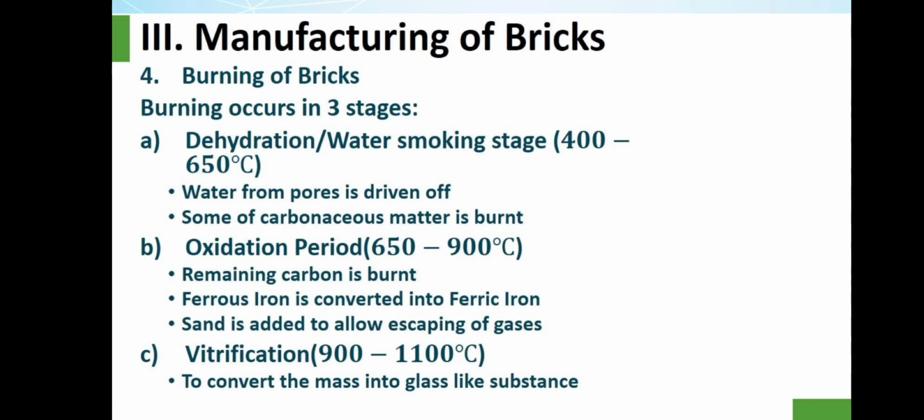Fourth, burning of bricks. Burning occurs in three stages: A. Dehydration or water smoking stage at 400 to 650 degrees Celsius. Water from pores is driven off. Some of the carbonaceous matter is burned.